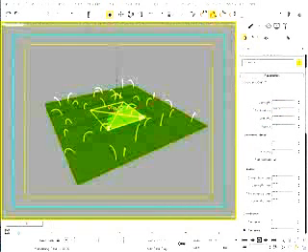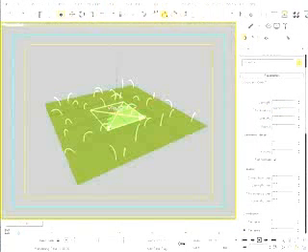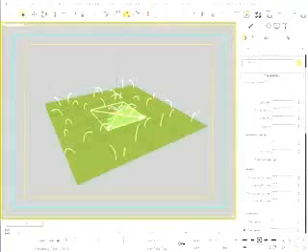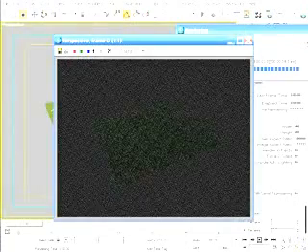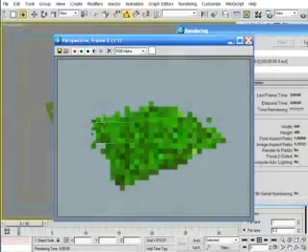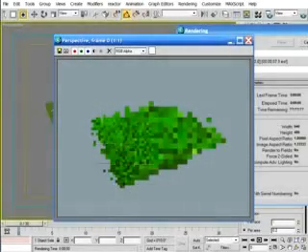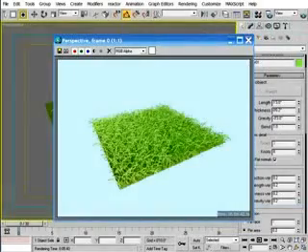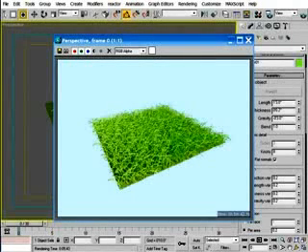If you use this feature, I recommend applying the same material to the fur object as you do to the object below it. And you always want to make sure you have an object below it, otherwise you'll see the background or some other object that you shouldn't really see. With a nice shadow casting light, you can easily create some realistic grass. And just remember that, like the VRay displacement modifier, this feature will definitely increase your render time, so use it wisely in areas that you can really benefit from it.